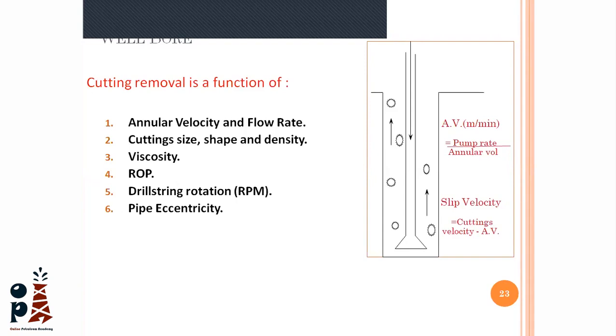It is the ROP, number 4. And guys, ROP is important in this case. Why? Because I cannot fill the annulus with cuttings beyond a certain limit and say to myself, hey, annular velocity is good, viscosity is good, it will be clean. No, guys. ROP is a very critical factor in cutting removal. And I have field experience in this ROP case. One time we were drilling in a surface formation, 17.5-inch hole, and surface formations are usually easy to drill. We had a high ROP, and the driller has to control it. I don't know why the driller made a mistake or maybe had bad instructions.